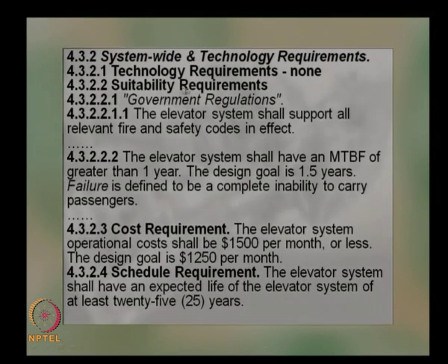Then there are suitability requirements about the government regulations. The elevator system shall support all relevant fire and safety codes in effect. The elevator system shall have an MTBF, that is mean time between failures, of greater than 1 year. The design goal is 1.5 years. Failure is defined to be a complete inability to carry passengers. Then the cost requirement: the elevator system operational cost shall be $1,500 per month or less. The design goal is $1,250 per month.